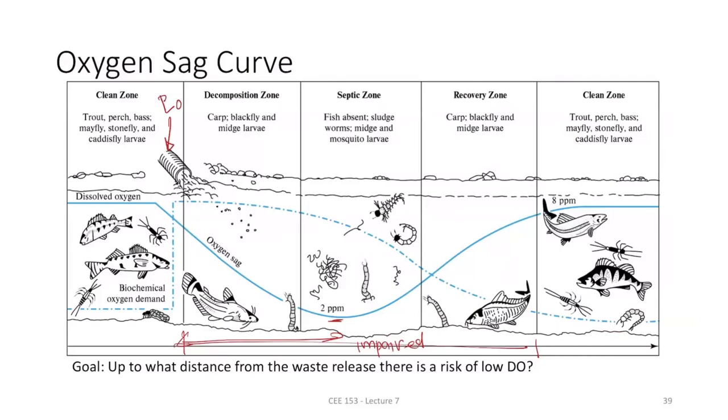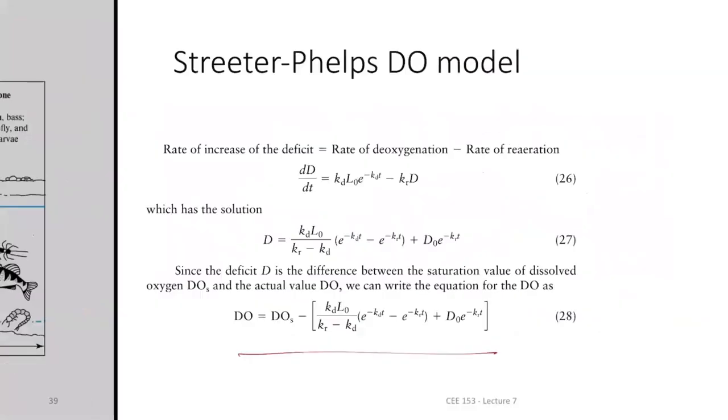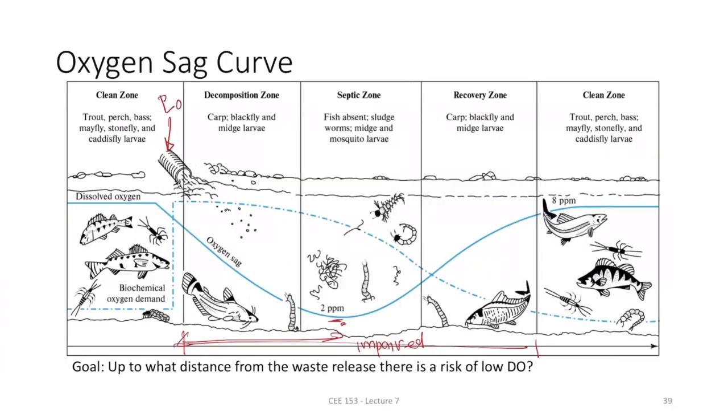Now the last one. The last concept is the concentrations, so we are calculating them at particular locations. Again, let's solve this one. We apply the mass balance. First of all, if there was no reoxygenation, this would behave like a batch, like a PFR, a plug flow reactor. And for a plug flow reactor, C(t) is C0 e to the power minus kt, where k is the reaction rate.